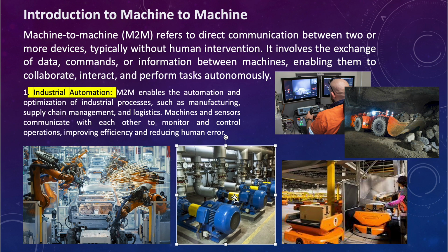Again, if we need to make this IoT, we can have pressure sensors. Not only here, we can have pressure sensors throughout the entire line, and that could be connected to a network, and it will properly monitor if there are any leaks or if there are any problems. This is a good example. These machines can talk to each other to measure the pressure inside the pipes. They can maintain the pressure.